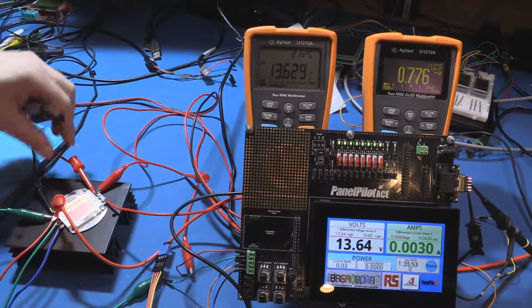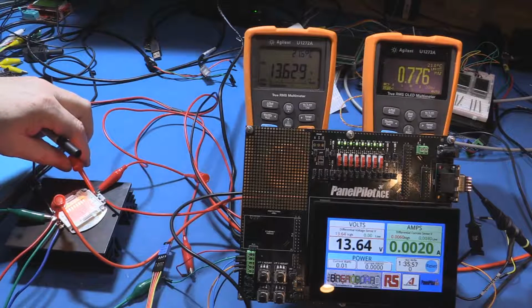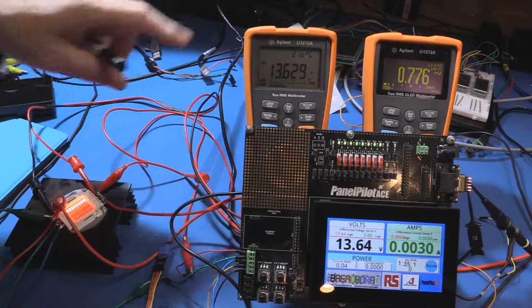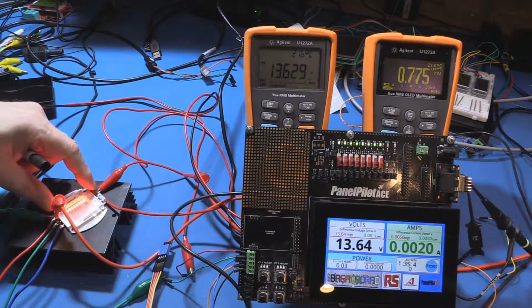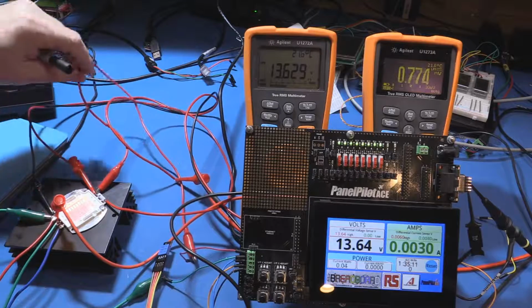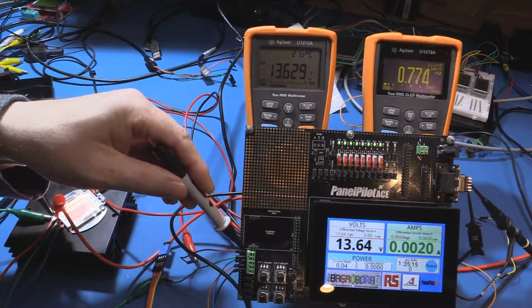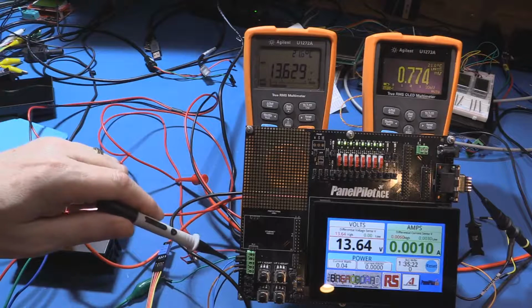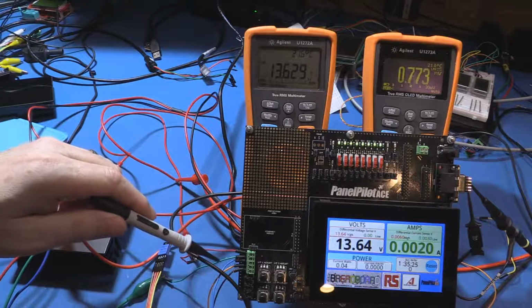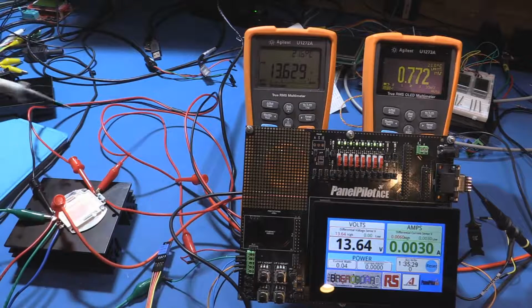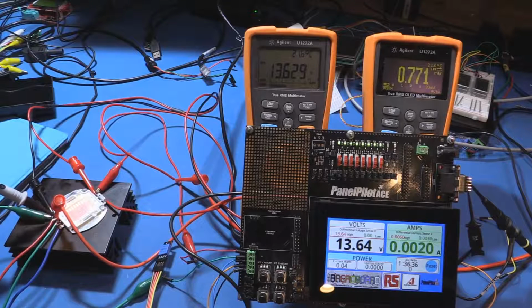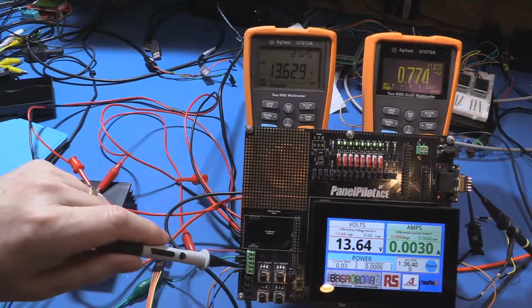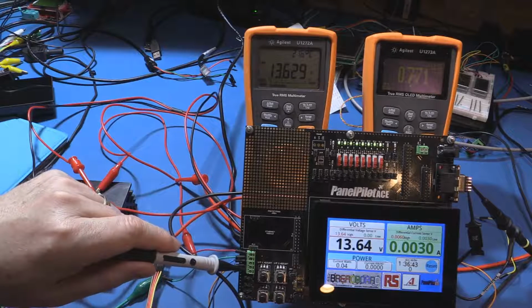Anyway, I've got one end of the LED connected to my meter, and I've got the other end of the meter connected, so it's directly across the LED so we can measure the voltages. Now what I've also got is a second cable, which is this one here, which runs down to the channel 1 analog input of the PanelPilot. The green wire here is the channel 2 input, which is effectively the low side of a differential display that I'm using, and that is going to the low side of the LED. All right.